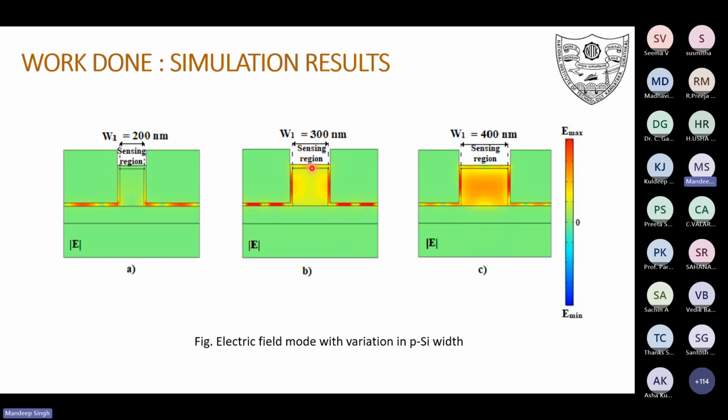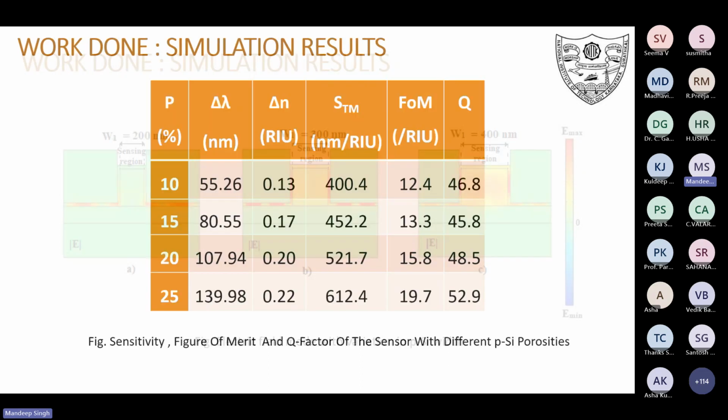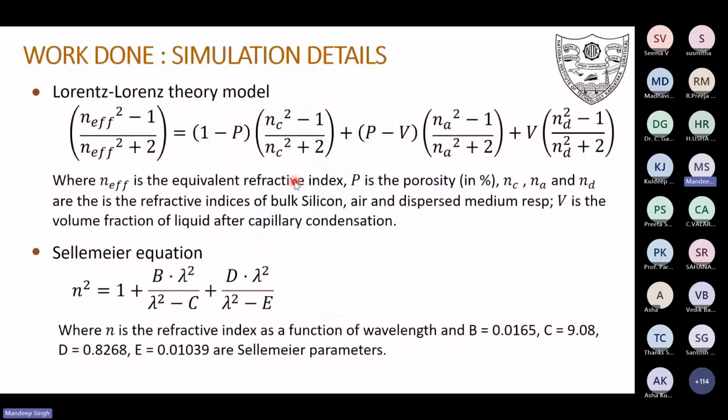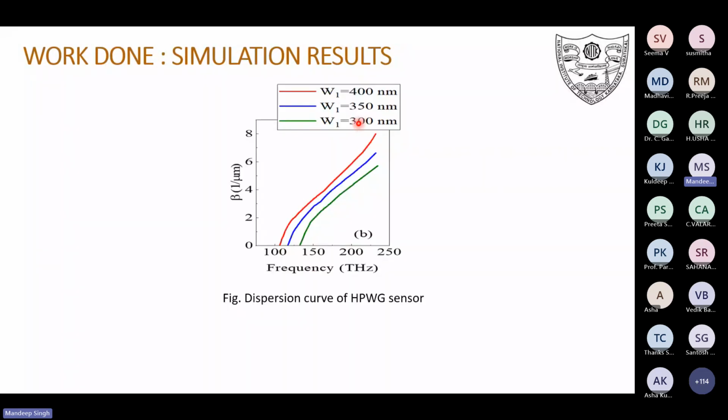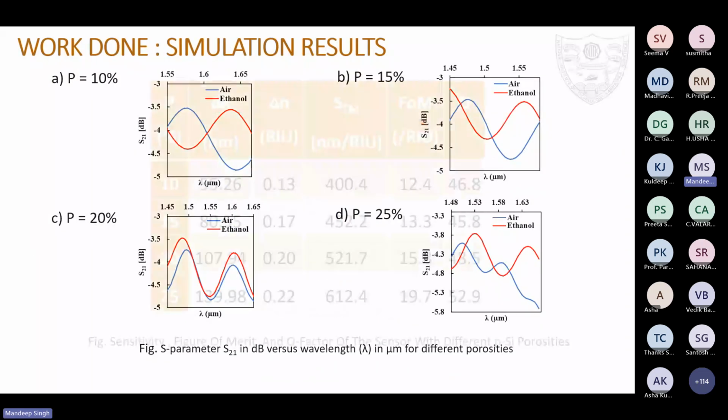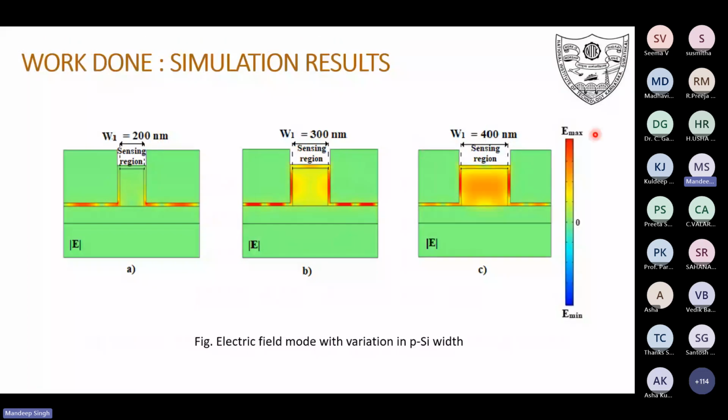So you can see now the modes are going very nicely for this type of structure. Even if you start increasing to 400 nanometer, and for this structure also, due to this reason only, we started our analysis from 300, because below this there is a decay out of the modes, then 300 to 400, and the same we have confirmed through the field plots. This is a surface plot of the electric field in volt per meter. So that is matching our result with the simulation.